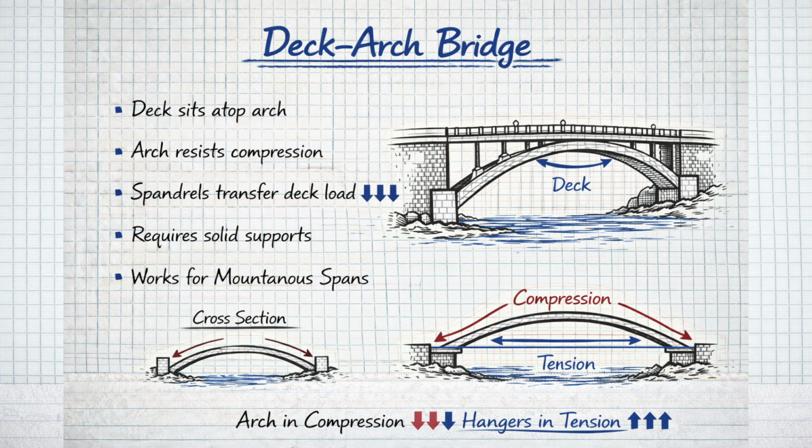9. Deck arch bridge. A deck arch bridge places the roadway on top of the arch. The arch supports the deck from below and transfers forces outward into the abutments. It functions as a strong compression system. This type is often used in valleys and gorges.